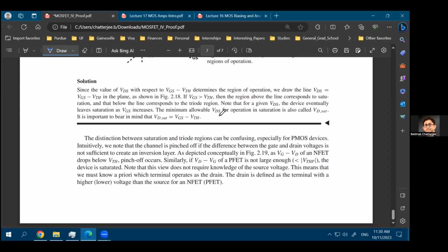What is the input of the MOSFET? The input is provided to the gate, and because it is an insulator, metal oxide semiconductor, there cannot be any current flowing into the gate. So if you are applying it to the gate, the input is always a voltage. You can get a current at the output, but your input is always a voltage.